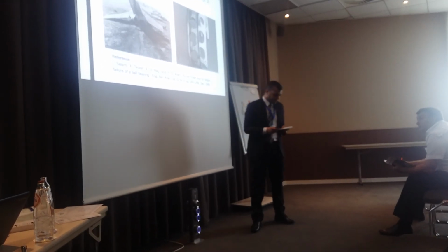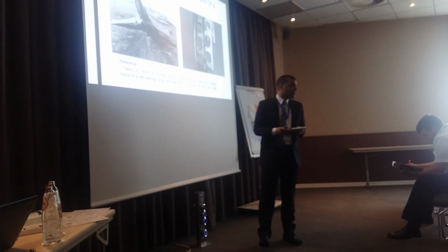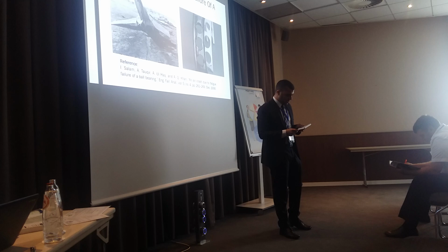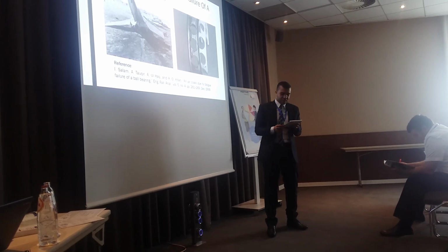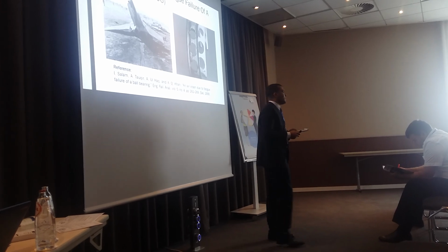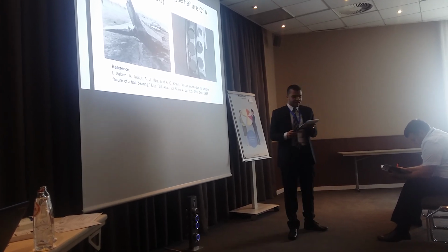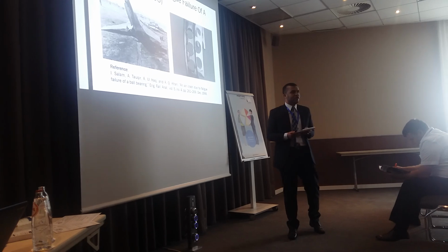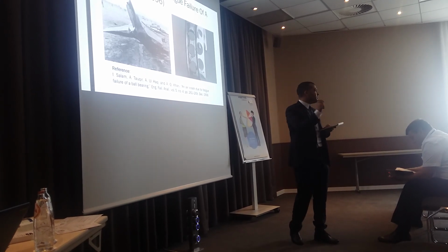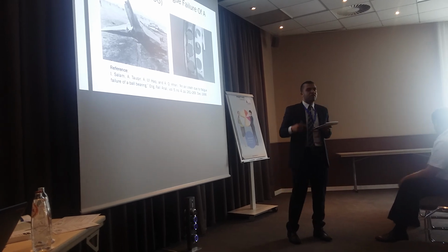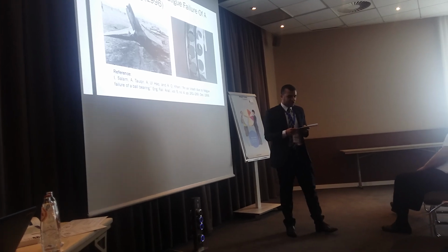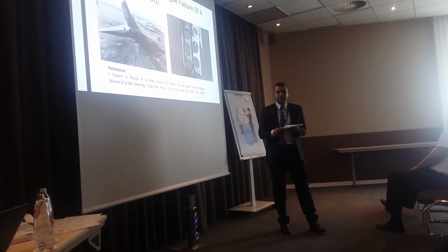Good afternoon, everyone. Sometime in 1996, a fighter plane crashed due to a fault in the compressor of one of the engines. The in-situ investigations found that the central bearing of the compressor shaft had failed before its specified lifetime. And the failure analysis showed that the cage of the bearing failed due to fatigue. A broken piece from the cage got stuck between the bearing bolts and the races, which made the shaft rotation difficult and led to the crash. Of course, early bearing fault detection and surveillance could help prevent such catastrophic disasters.